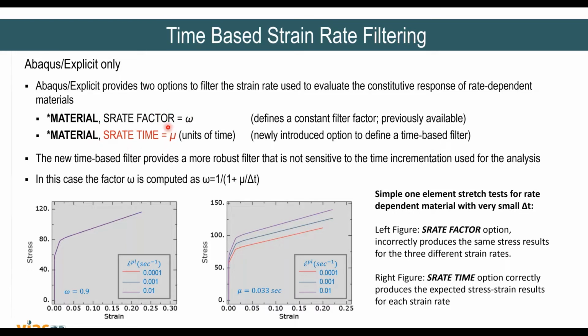In this version, we have given another option, rate time, which gives you the option to define a time-based filter. This new time-based filter provides more robust filtering that is not sensitive to the time increment used in the analysis. What you see on the left-hand side is a comparison between the two options: the previously available option and the new option.